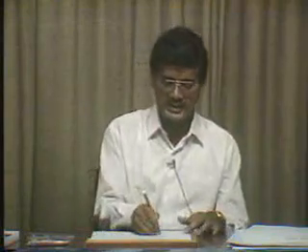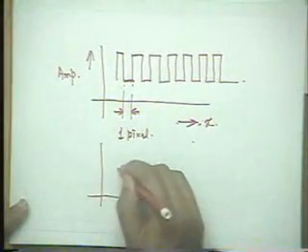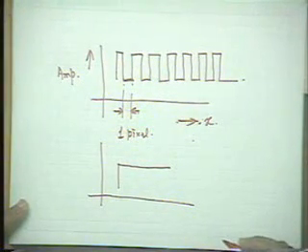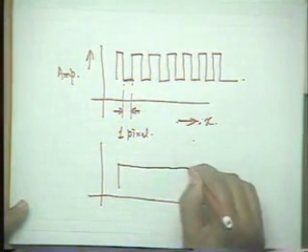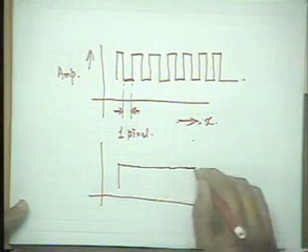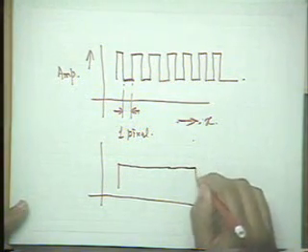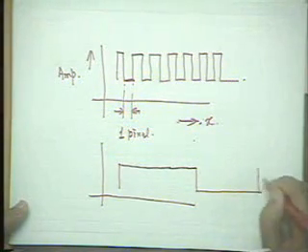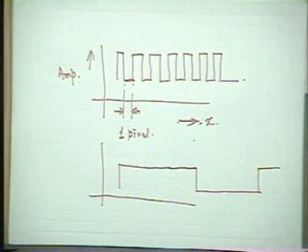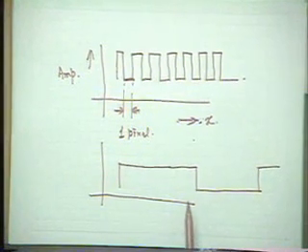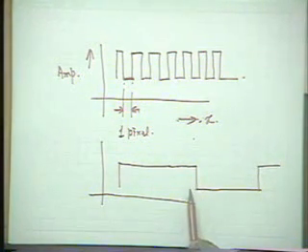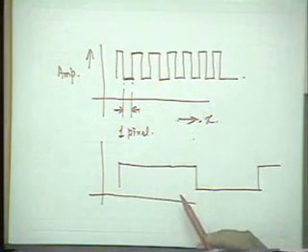Now, if we take yet another signal, where that particular signal is bright for several pixels, maybe for 7 or 8 pixels it is at the bright or high intensity level, and for the next 7 or 8 pixels it is at the low intensity level. If we have a signal like this, clearly this kind of signal has much lower frequency content, or rather this is a much lower frequency signal as compared to the earlier one.